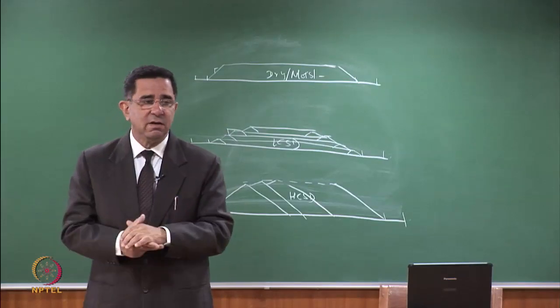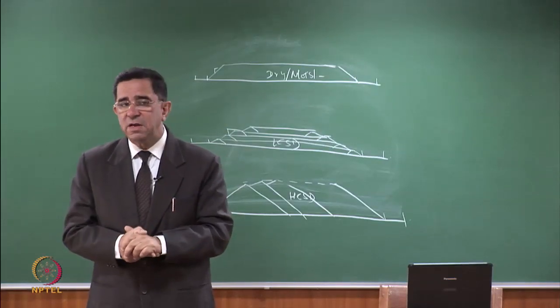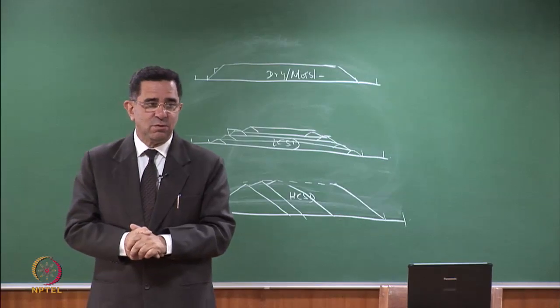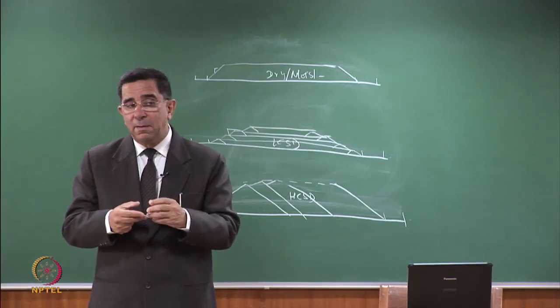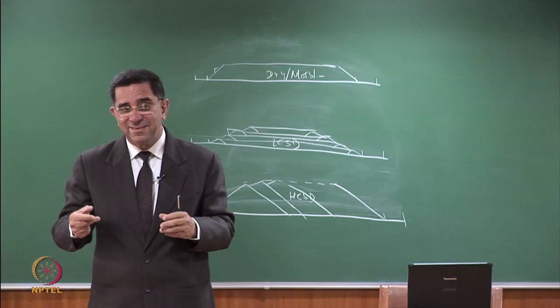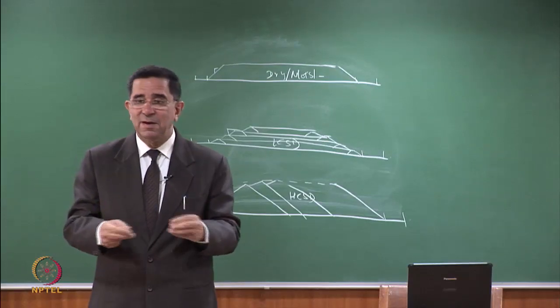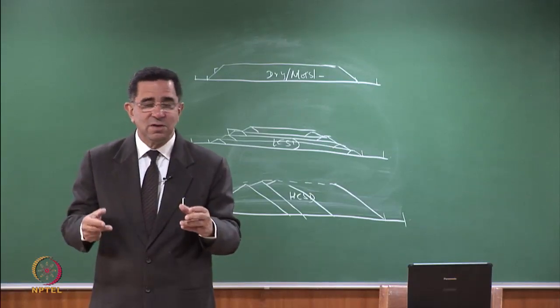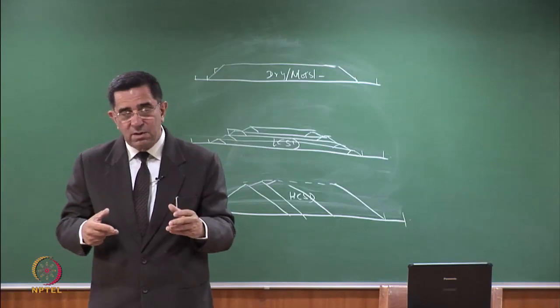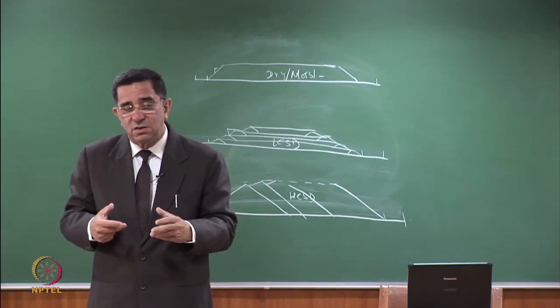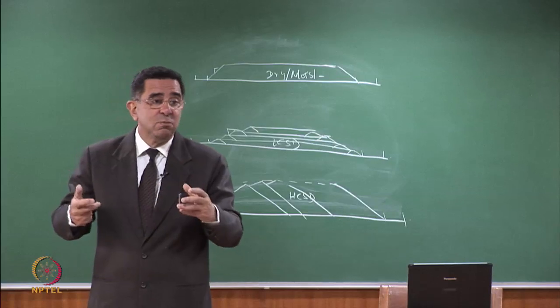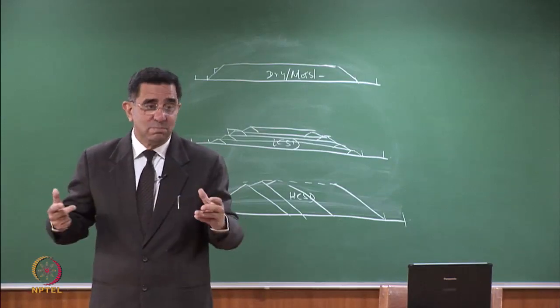So lean slurry or lean concentration slurry still remains the main method of disposal, because maintaining the pipeline is much simpler. It's very lean, it doesn't cause that much erosion, and there are less breakdowns. But with high concentration, there's an issue of breakdown. And even with a boom spreader, please remember, there's just one boom.